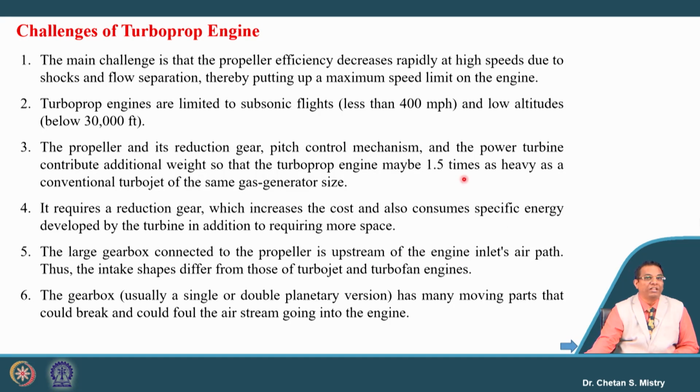The main challenge is with the propeller efficiency, because when my speed is increasing, that will give the shock formation and flow separation, and that will lead to a limitation in terms of maximum speed.